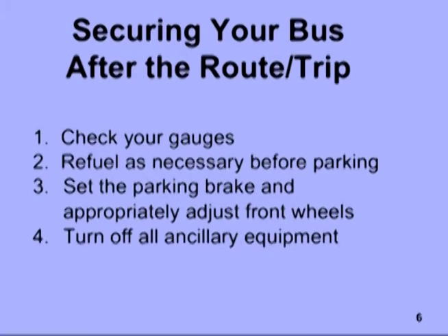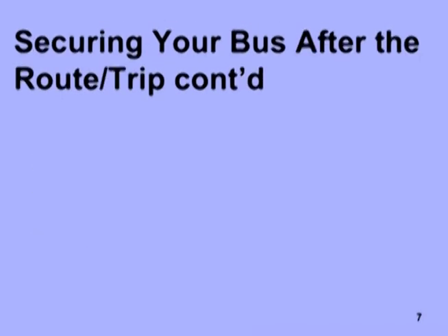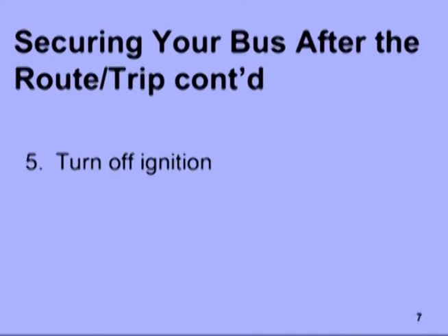Turn off all your fans and other ancillary items. While most equipment ceases to operate when the bus is off, don't assume that your headlights go off as well. They don't. Continuing with securing the bus. Turn off the ignition. Make sure that the ignition is in the off position. If the key is not truly off, it may result in equipment continuing to operate and drain the battery.